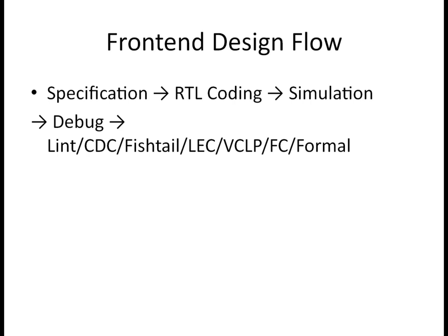For that, in the industry, there are basically two vendors. We are using the Synopsys tool called Spyglass Lint. That lint tool will make sure the RTL is following the coding rules and design guidelines.